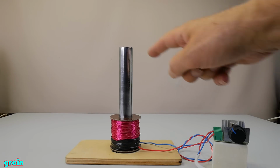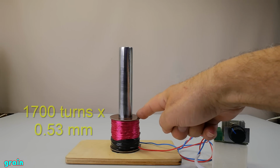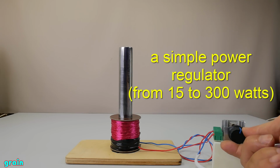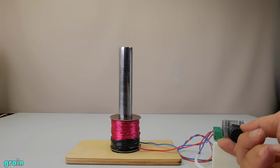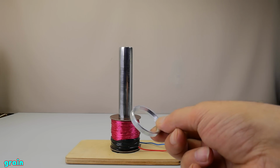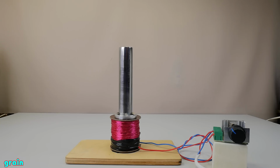Well, let's now see how an alternating current of 50 Hz affects our ring conductor. I made an electromagnet with a core from a steel cylinder with a diameter of 25 mm and a coil with 1700 turns with a wire of 0.53 mm. On the right is a simple power regulator. The power of the magnet is adjustable from 15 to 300 watts.